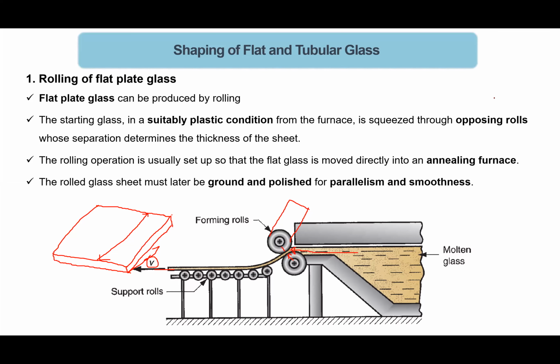Are you talking about this, Rana? Actually there is a temperature difference between the molten glass and the solidified form before and after the forming rolls. So we have to maintain some minimum time within the limit. If we cross the limit, then it will solidify itself at the roller part. It will be separated, right? Yes, this one is solid. That's why you have to ensure the flow of the molten glass.